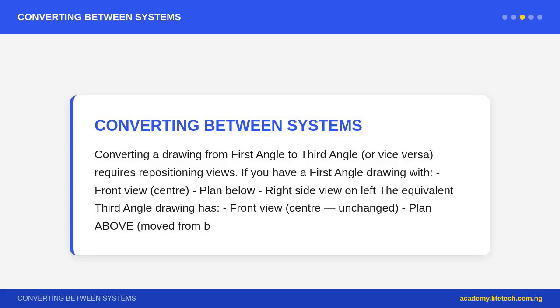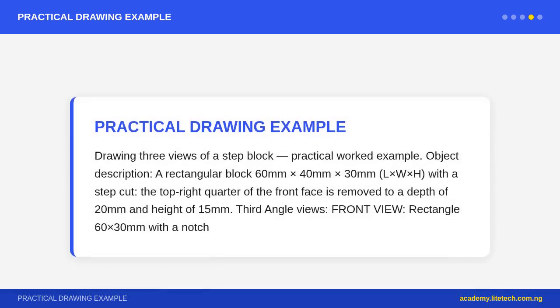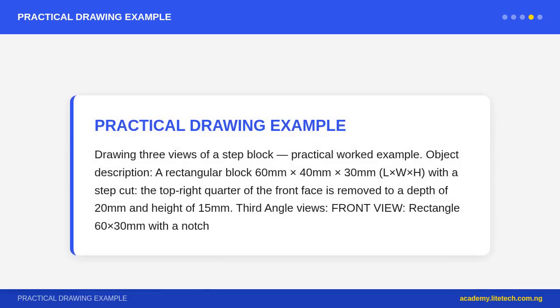Alignment: third angle. Plan is above front view, horizontal projection lines connect them. Right side view is to the right of front view, horizontal projection lines connect them. 45 degrees miter line at the intersection allows widths to be transferred between plan and side view.